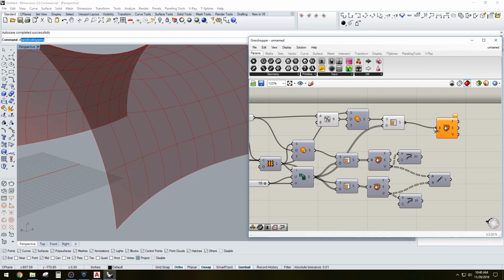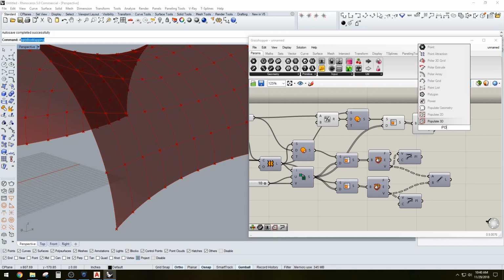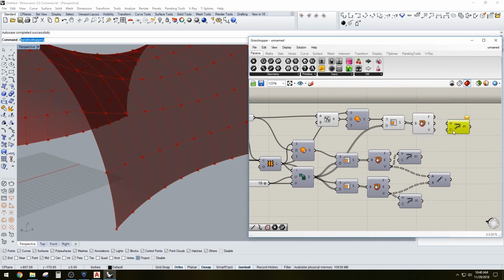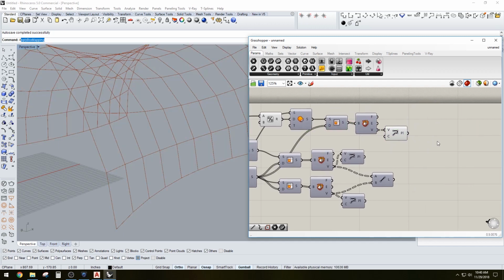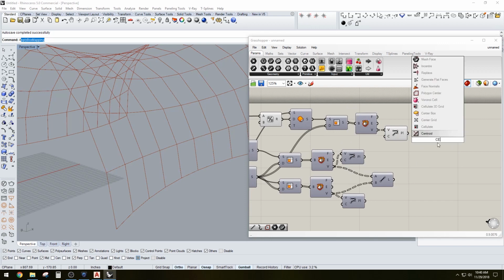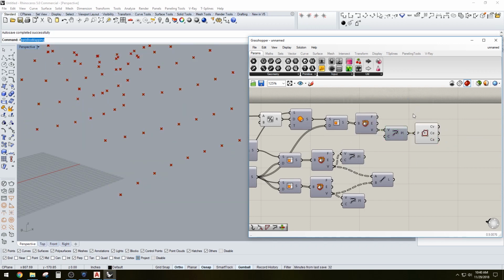Let's deconstruct the B-rep to get the vertices, which are the points at the end, and let's create a polyline that is boolean to true. Sorry, it's a little bit off screen. You want to set that to true, and we put these vertices here, creating those polylines that are in the center. And from here we create a center point in that polygon. So we found that polygon center. Perfect. We can hide that.